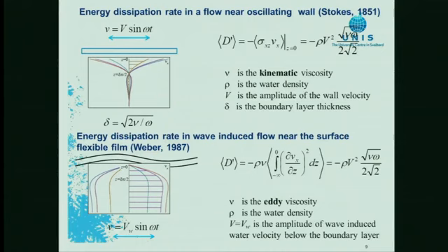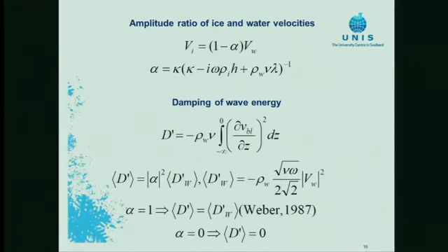The energy damping is calculated with a standard formula like an integral over the thickness of the boundary layer of the second power of velocity gradients, and it is expressed with this formula and depends on viscosity and frequency. So then further I will deal with effective viscosity, or I will call it eddy viscosity.